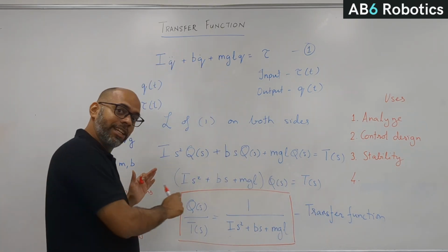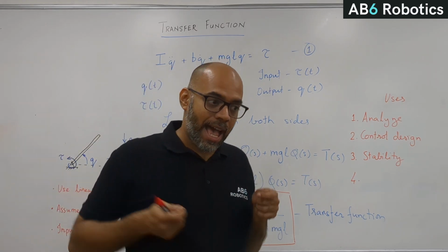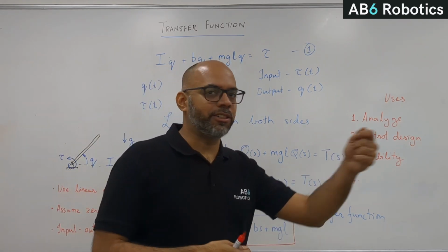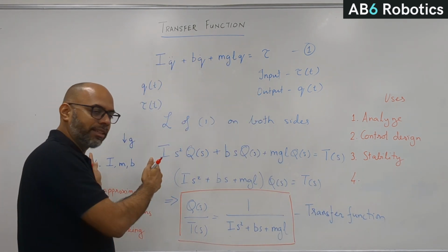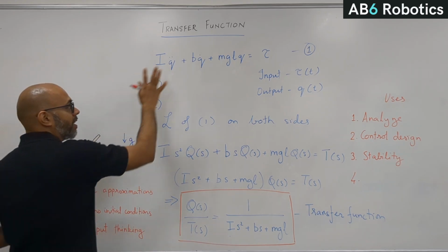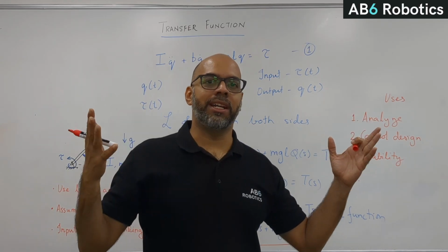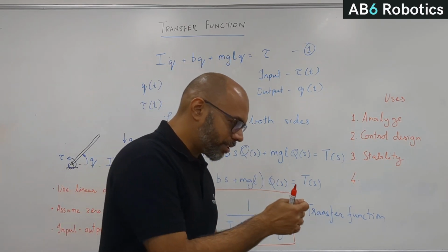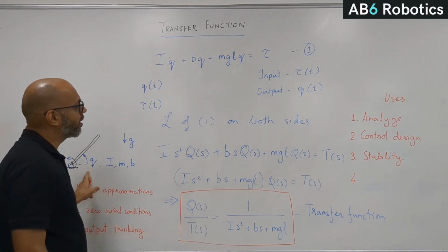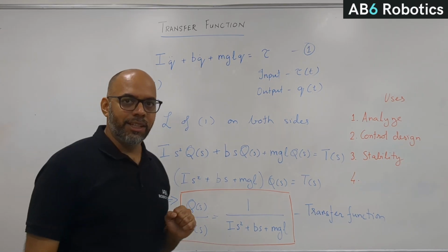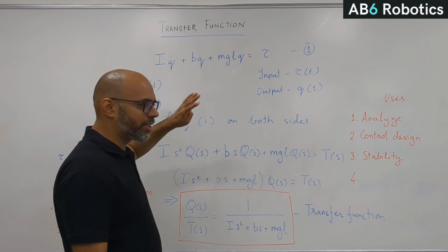Then you write another differential equation representing how the motor torque changes as the motor voltage or motor current changes. Again, you can write down the differential equation representing that. Now, if you wanted to find out the combined effect of, if I apply voltage to the motor, how does it affect the torque, and consequently, how does it affect the joint angle? If you wanted one compact representation of that, you would want to combine both those differential equations.